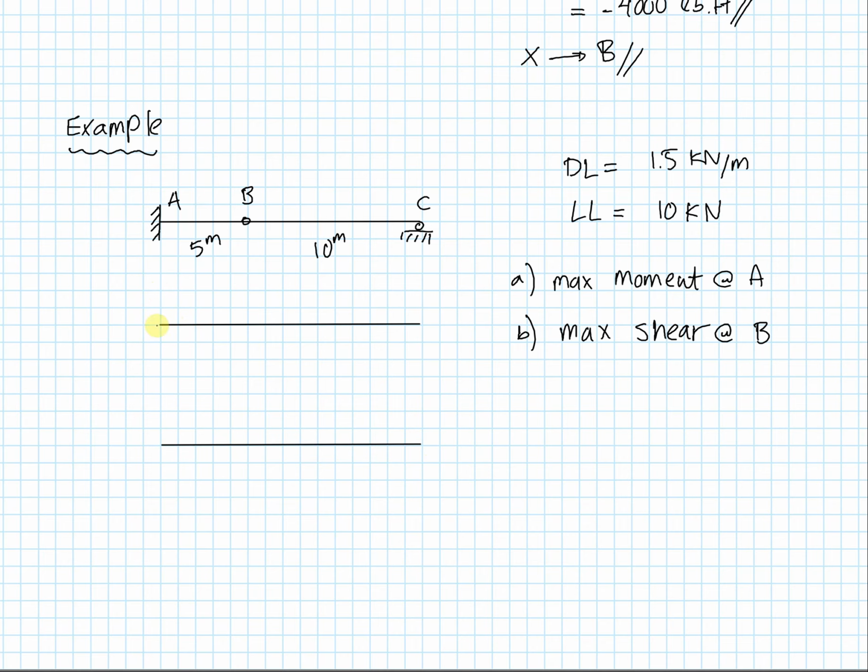So for bending moment, I am interested in MA and how it's going to vary with different positioning of loads. For MA, when I introduce a hinge at location A, there is going to be a drop, since there's also a hinge at location B and there is a roller at C. It's fairly intuitive, right?